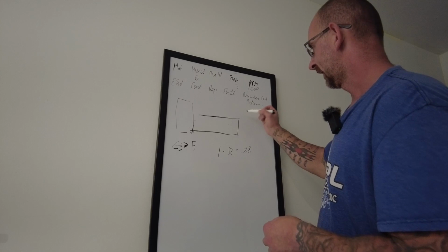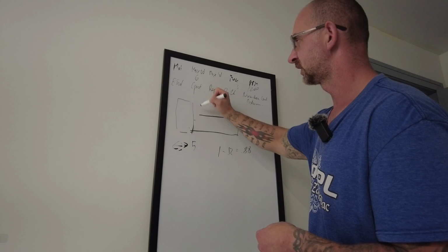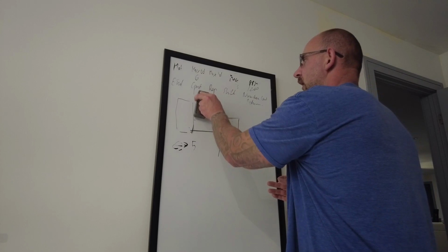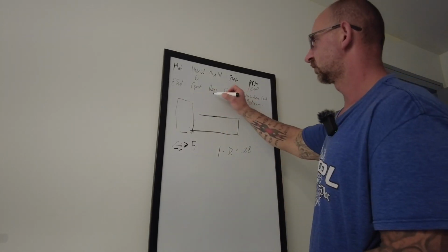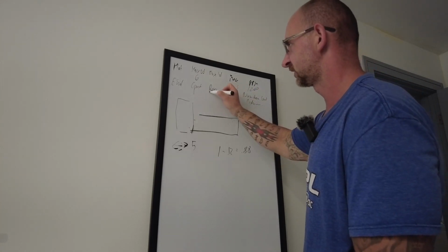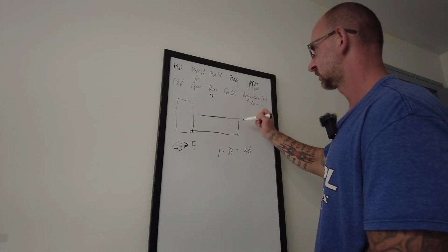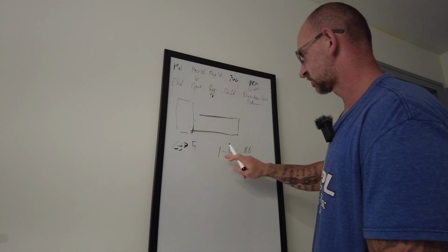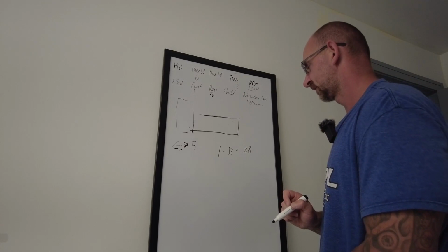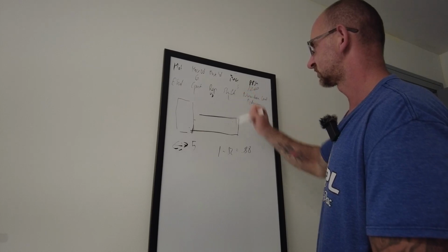So what happens is, I'm going to say yes, I want to continue. From what I remember, continue is 1, and I don't want to continue is 0, right? And it's going to ask, how many times do you repeat? So if I've got 5 washers, I'm going to say repeat 5 times, okay? And then it's going to say shift. Since the washer is 880 plus the cutoff, that's going to be 1 inch. My shift is going to be 1 inch.